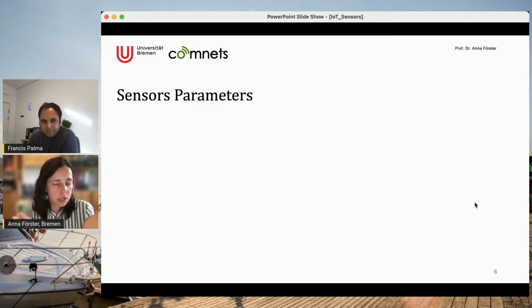In Arduino, for example, some pins are reserved for analog, some can be used for analog and digital, and some are reserved for digital only. So you have to check this for your platform in order to know where you're actually allowed to connect this or that thing. I guess PyCom also has some dedicated pins for analog and digital signals. I'm pretty sure about that, I just don't remember the numbers.